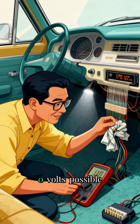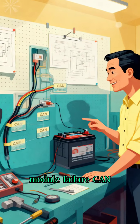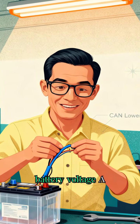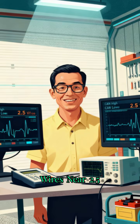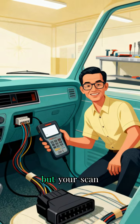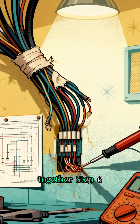CAN low toward 0 volts. If CAN low stays near 0 volts, possible causes include a short to ground or internal module failure. CAN low near battery voltage. If CAN low measures close to battery voltage, suspect a short to battery voltage or a failed module. Both wires near 2.5 volts with no communication. If both CAN high and CAN low stay near 2.5 volts, but your scan tool cannot communicate, check module power and grounds. Network circuits may be shorted together.